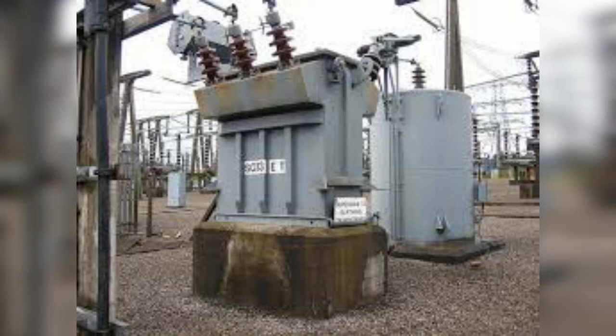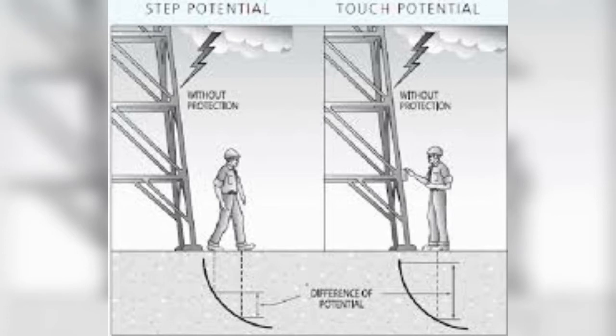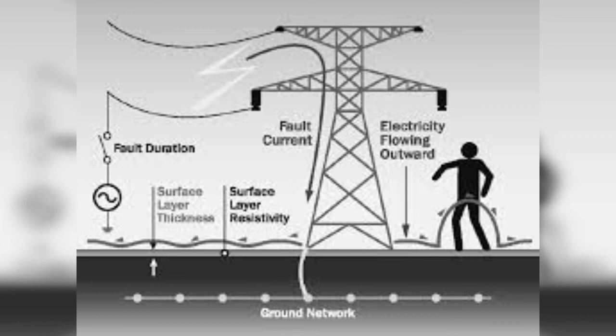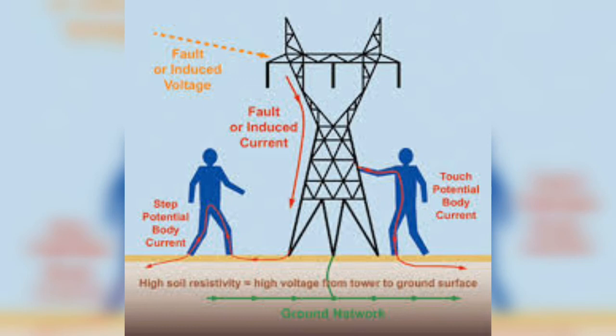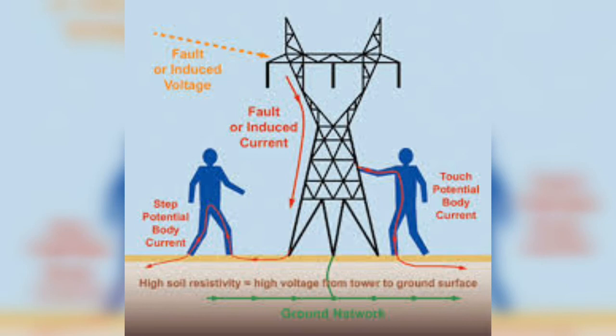A substation with a relatively low grounding resistance might be dangerous, while another substation with a high grounding resistance might be safe or could be made safe by careful design. Here, a high resistance means something like 3.5 ohms.